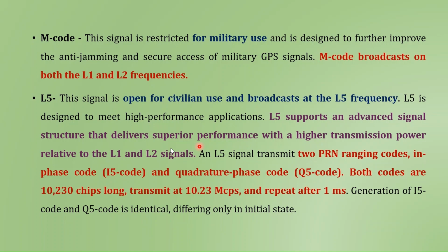And both the codes have the same length, that is 10,230 chips long, and are transmitted at 10.23 million chips per second and repeated after 1 millisecond. So both these codes are identical but differ only in their initial state.